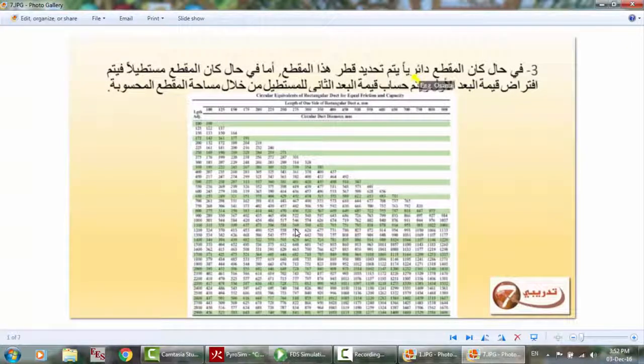Please choose the dimensions so that you get the aspect ratio 3 to 1, 2 to 1, or 1 to 1, and you have to know exactly what ducts, or dimensions, are provided by the companies. Okay, and you have to read more catalogs, or know what's going on in your country in this field.